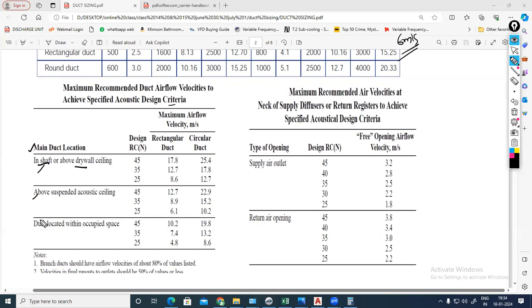Normally, that one we are using in movie theaters and sound recording studios only. Ceiling also, we will have seamless wall and floor, and they will also provide acoustic insulation. But normally we will be selecting the third condition, no ceiling condition, where the duct is located just above the false ceiling, a gridded false ceiling. In a false ceiling we have some openings, a normal condition. So I am selecting the third condition.